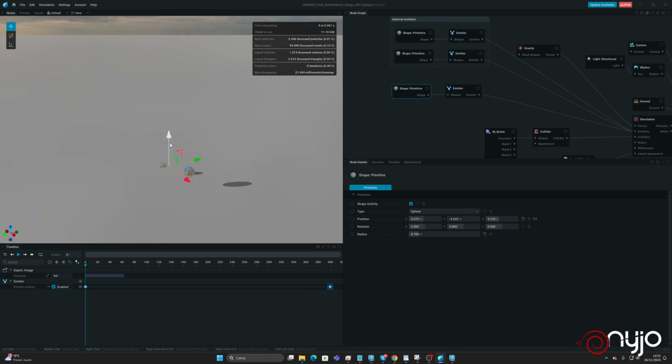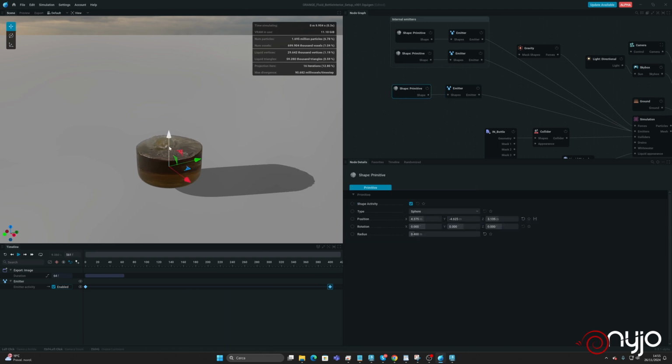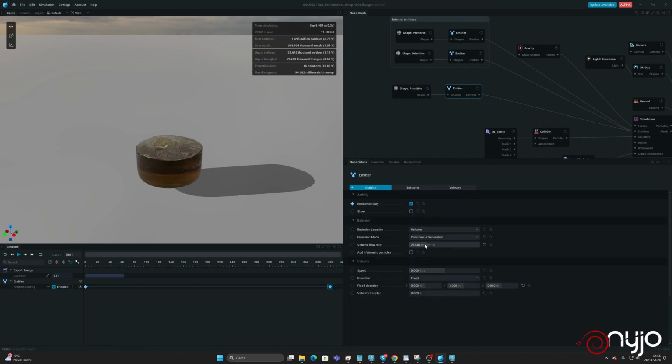Let's go down and try to help the other emitters. Okay, but it needs to be smaller, so let's try with 0.04, but we give more flow rate. So we have the beginning of the fluid simulation, then we have the new one that is helping to add fluid, but we have to make it lower, and let's try 35, and again let's make a test.